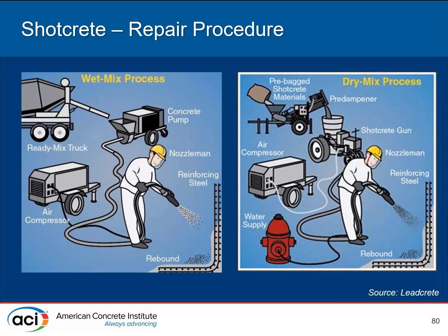Even though, as I said, wet process is for big areas, dry process for small areas, it's more important the contractor is comfortable with what they're doing, and I don't like, as an engineer, controlling the way they're doing stuff, what's more comfortable for them. You end up with the same product at the end of the day if everything's done right, and you still get rebound with both situations.